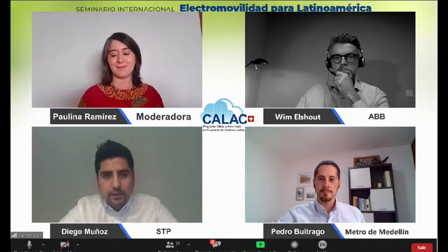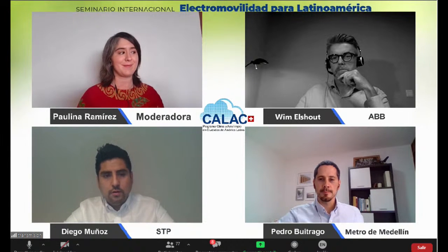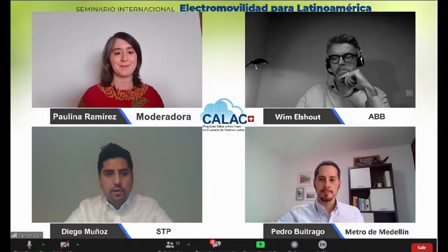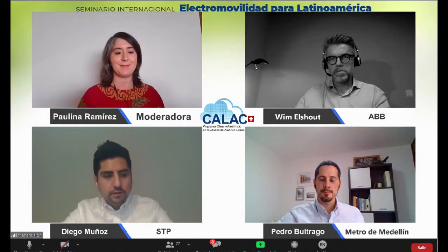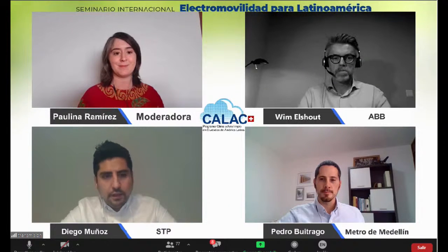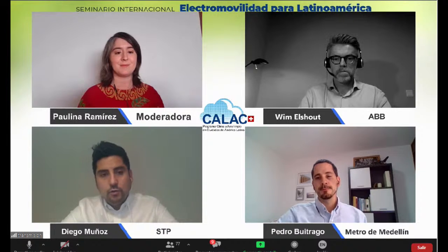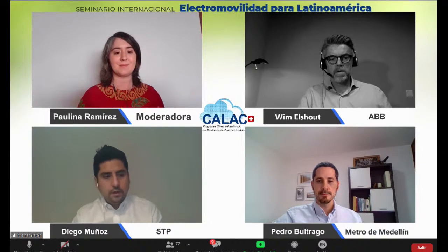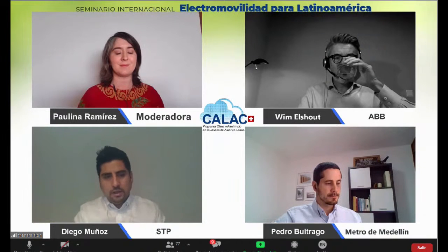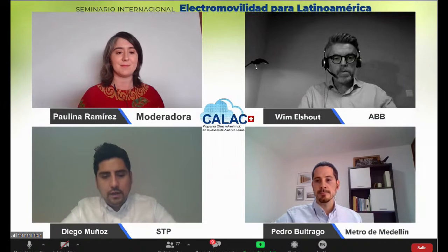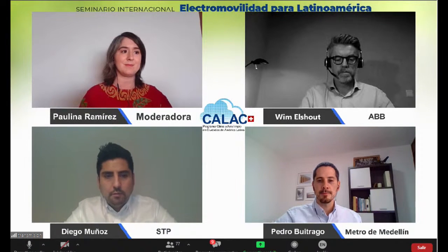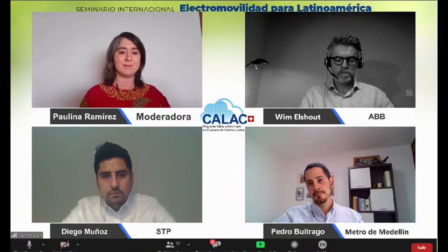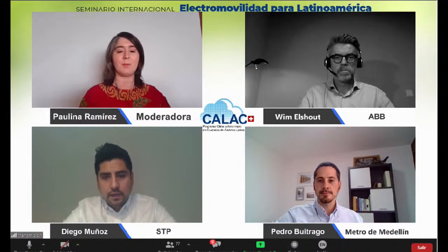Okay, regarding the techniques, something that you have to be careful about when driving is when you get out, because the electric buses are very quick. So when they depart, they're very powerful. Therefore, you need to have precautions there, because it goes very fast and the consumption is also according to that. If you do it gradually, of course, the consumption will be a lot lower. Now, regarding regeneration, the data regarding the manufacturers, for example, what you can obtain in a specific trip, you could have 3 or 4% of this specific trip for regeneration of the battery.